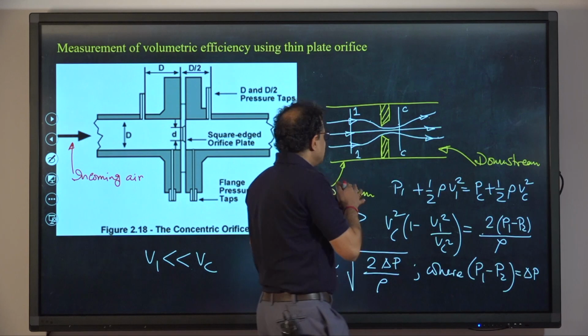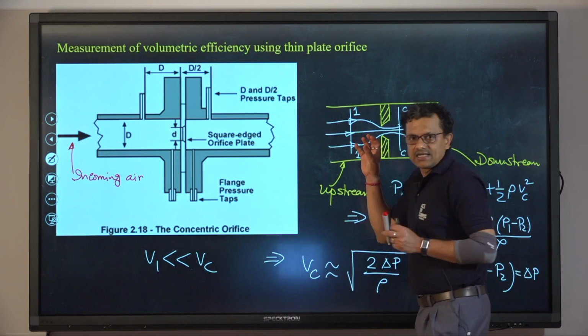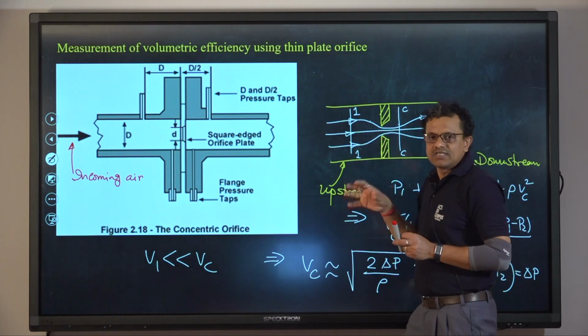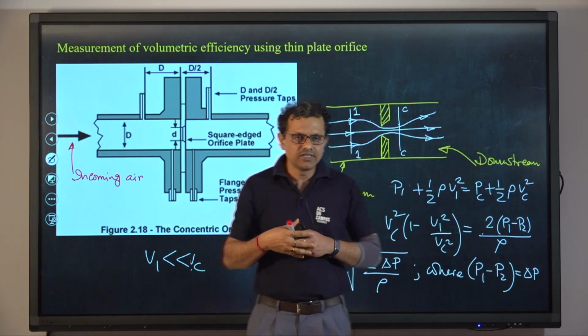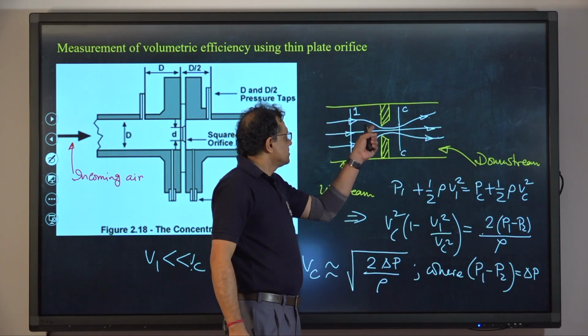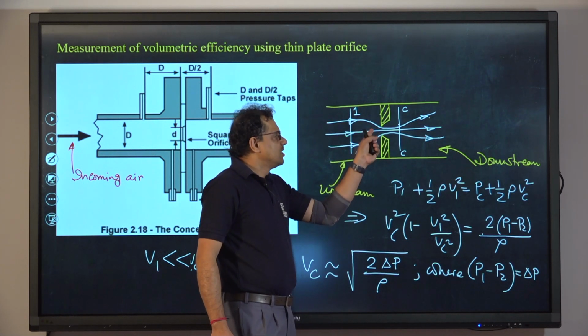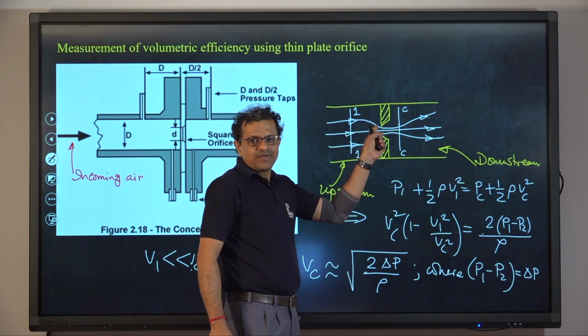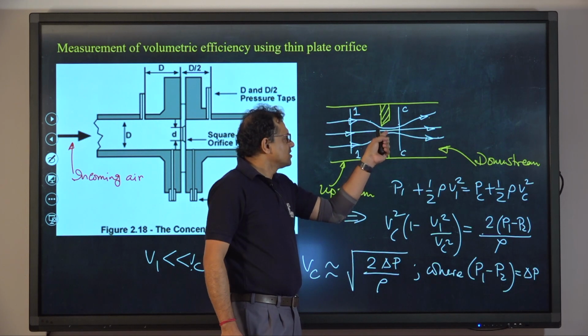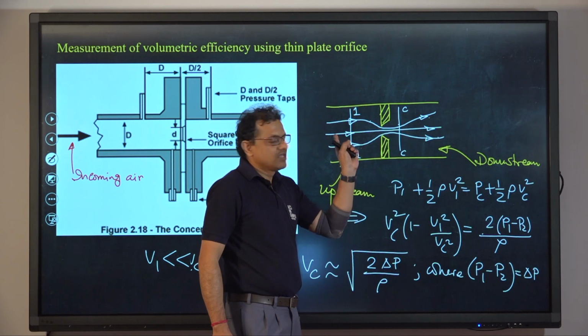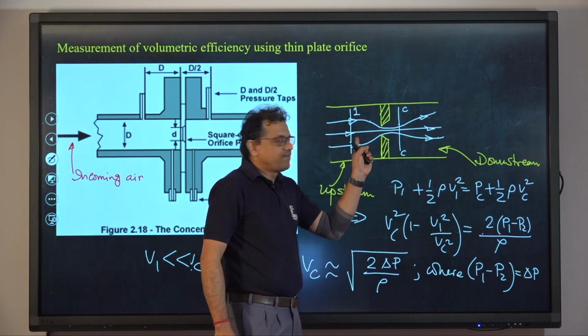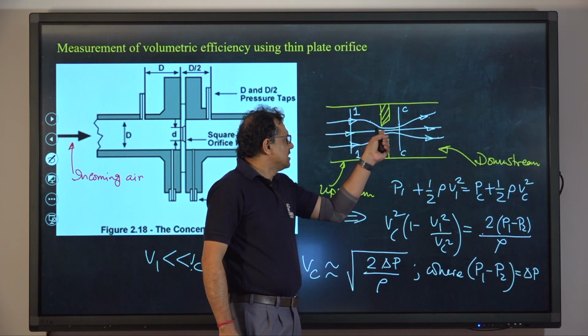because we know that from the conservation of mass or continuity, as the flow approaches the small gap, then certainly to satisfy mass conservation velocity will increase, because assuming that the density is remaining the same in incompressible fluid flow, velocity will increase.